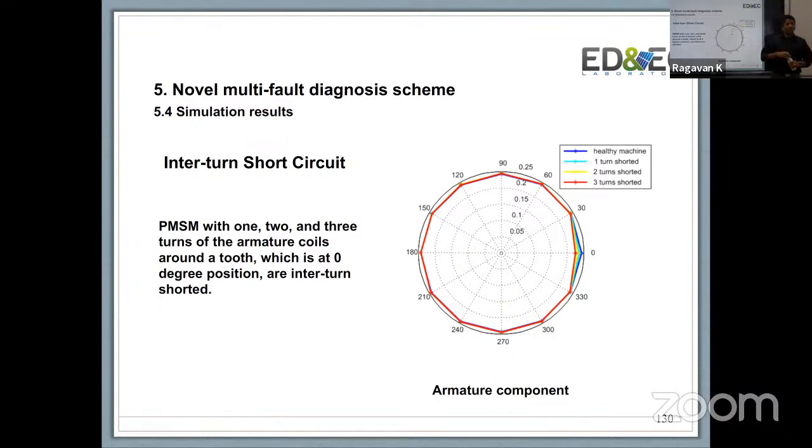Think about the fact that your power electronic converter is tied to your phase winding. To the very least, you are going to couple your power electronic response, the harmonic response to the power electronics, with the response that you're going to get from the voltage. So if you're measuring your terminal measurements, you don't know whether you're measuring the harmonics because of the motor or because of the power electronics. So you have to have a system that is isolated from at least the power. That's one of the reasons why we went for the surge coil.